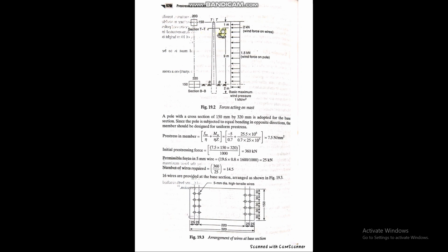If, say, the right side transmission wire snaps, meaning it breaks away, and the left one is the only one that is connected, then there is certain eccentric loading on the structure. We have to consider that as well. In certain cases, it may lead to generation of torsional loading in the prestressed pole, so we have to take that into consideration too.